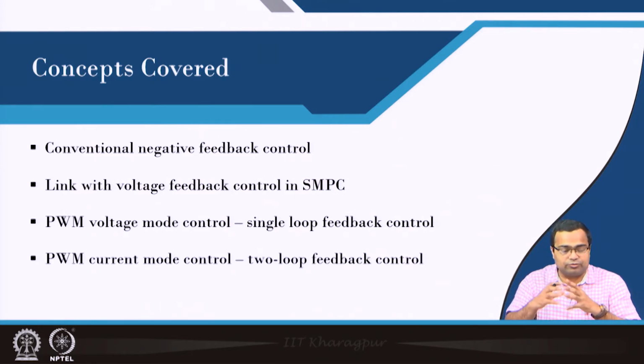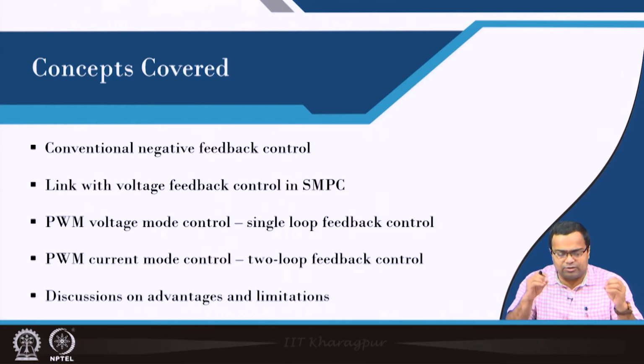Then we are going to talk about PWM current mode control, which is a two loop feedback control. And finally, I want to discuss some advantages and limitations of these multi-loop and single loop feedback control methods.